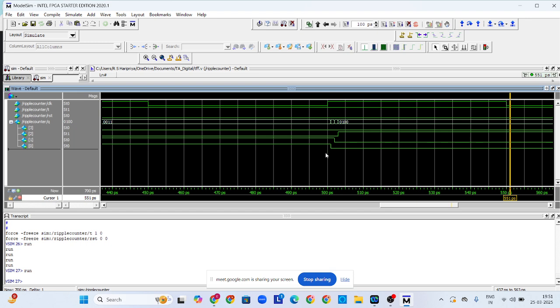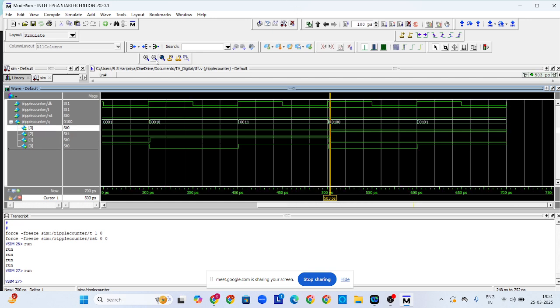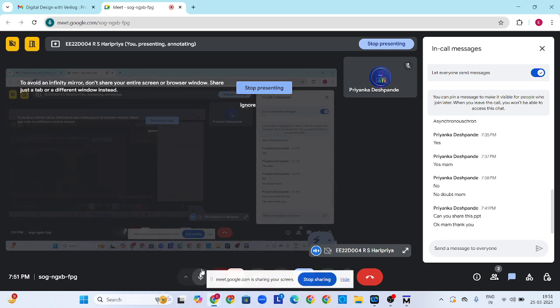See, there is some delay with respect to where the clock edge has occurred, and with the 0th flop having this much delay, the next flop has a little accumulated delay, followed by the next flop. So there is delay because of this rippling of the output as the clock to the next flip-flop. I just wanted to show this too.